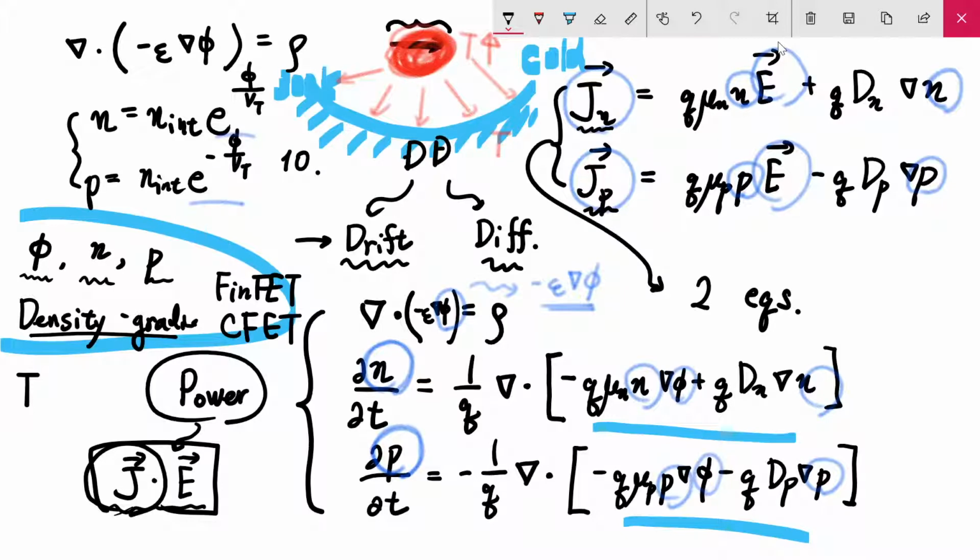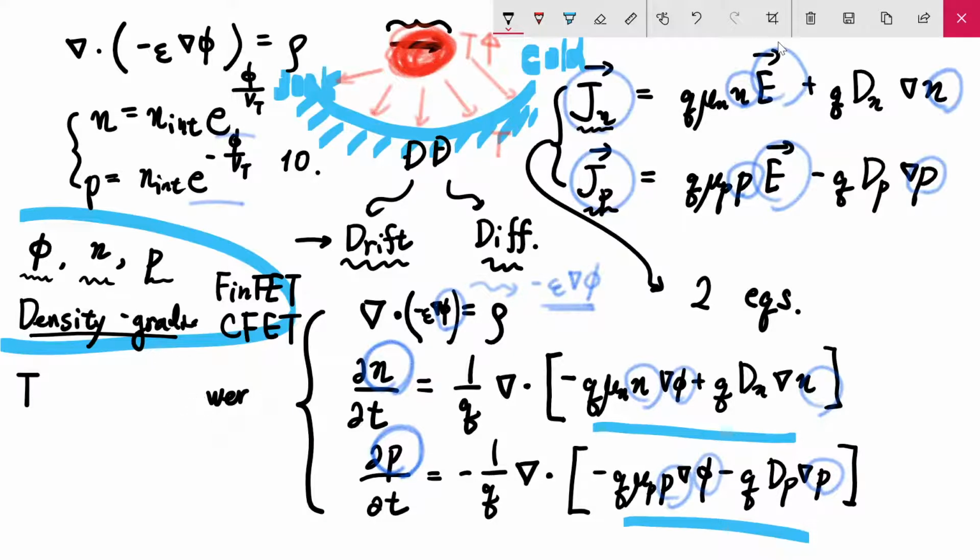For example, 300 Kelvin in many cases, or 350, or anyway, in conventional cases, we use a constant temperature. However, if we consider such a situation, so-called self-heating, then we have to consider the temperature of our lattice as a function of position. So this part we have 350, and here we have 320, and here we have just 300. Those calculations should be done.